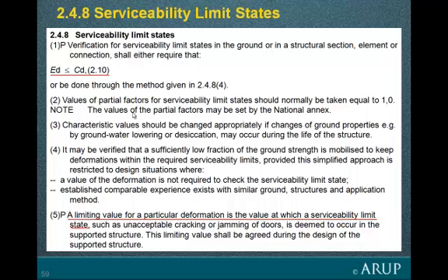For serviceability limit states, the requirement is often slightly different. It's that the effect of a structure shall be less than some limit, called here Cd. So this could be the effect of the loading, rather, a calculated settlement, for example. It has got to be less than a limiting settlement. That quite often would be the approach.